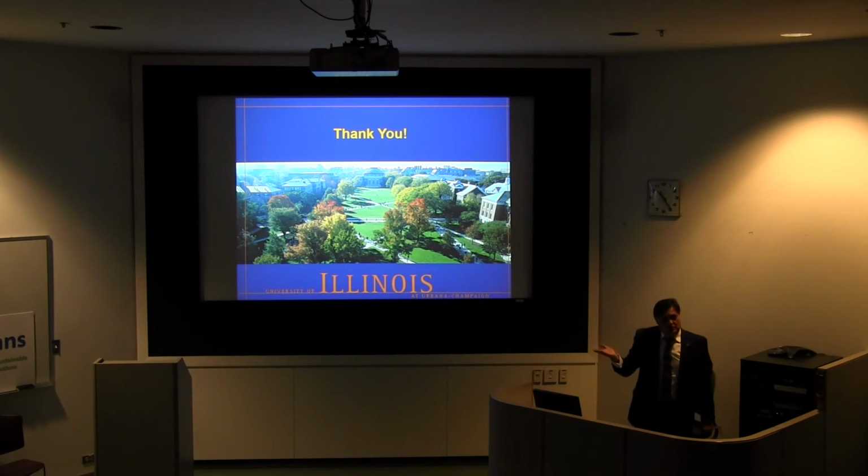Yes. So it's always calibrated to the surface. So if you don't want to see that pothole at all, what you can do is calibrate to the surface, and anything above the surface, you can just take out. So in that case, it will appear to you as if you have a spot where you have a much thinner pavement. Yep.